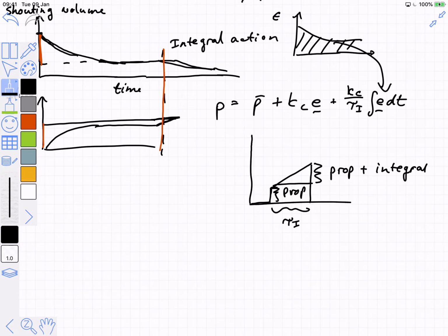If you say, obviously it's not just from the beginning of time, the answer is actually, in most cases, it is just from the beginning of time. But the beginning of time for a controller starts when it turns on. So remember, you turn this controller on, and at that moment, error is 0. At that moment, it starts with a 0 integral, and then it goes from there.